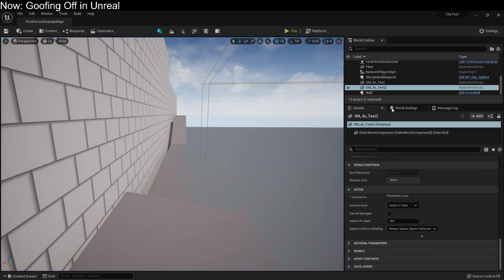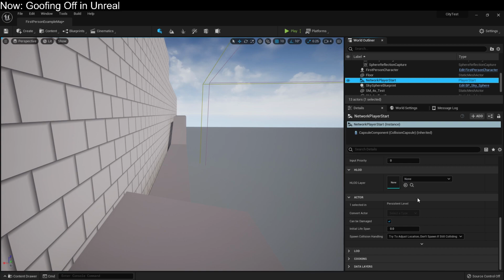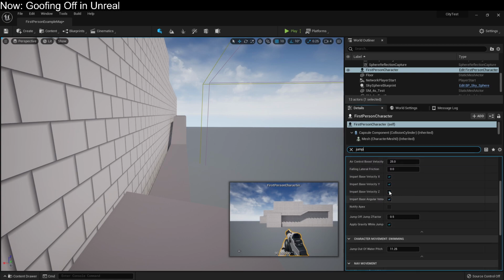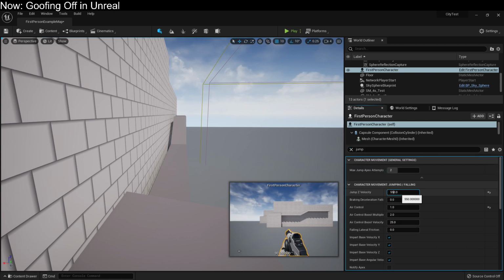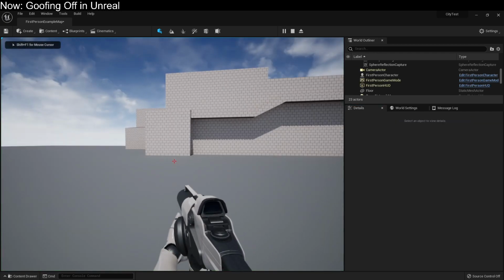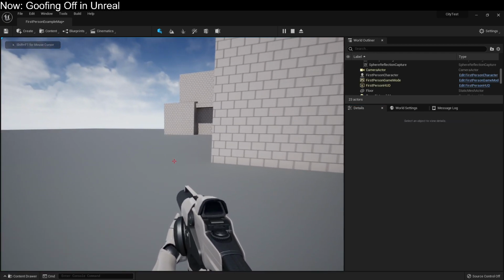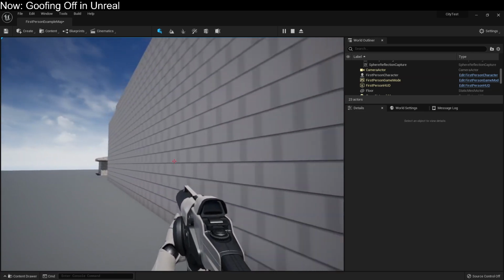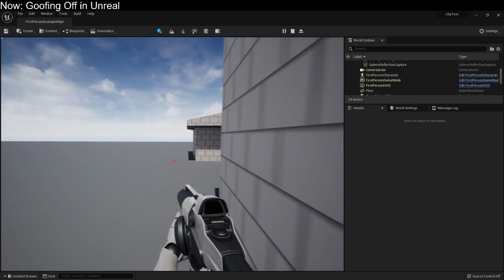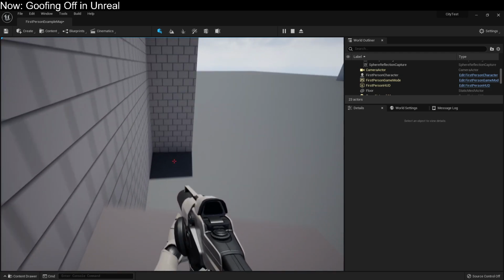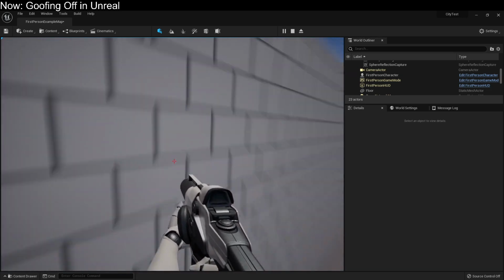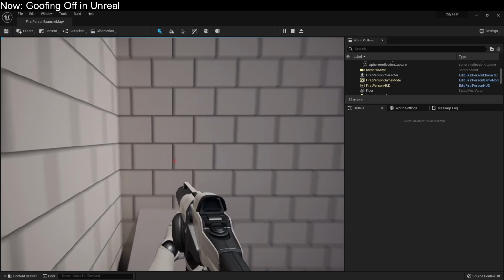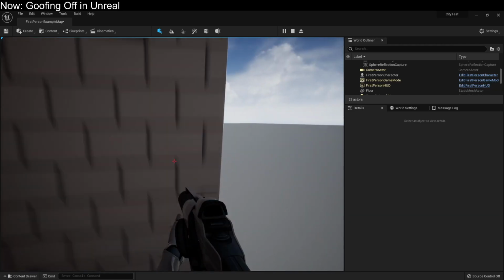Let's go ahead and nerf our jump just a little bit more. That's the player start, that's the character. Is there like a jump? 550. Let's bring it down to 540. Basically, I want to be able to clear exactly like 2.1 level gaps, which means I want to be able to jump like 7.1 meters with a double jump. So that's what we're aiming for. 7.2 meters maybe, but not 8. See? Not 8. Yeah, that's good. I like it.